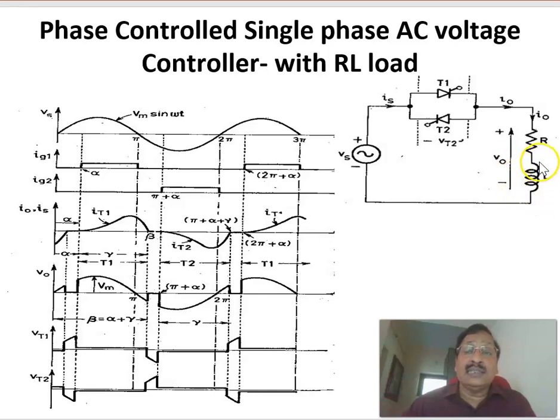Even though the current is not going to zero here, because of the energy stored in the inductor, and the voltage across the inductor, the already conducting SCR gets forward biased and continues to conduct. And because of this energy, the current is discharging, or decaying.